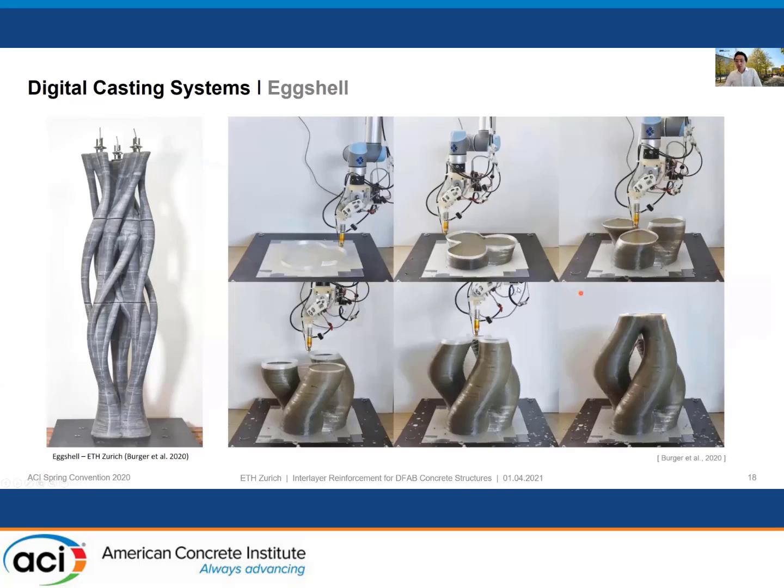On this slide, you see, I think, the Excel technology. Here, the minimum formwork is a 3D printed ultra-thin plastic formwork, which at the same time is filled. Then the formwork can be removed after casting, after the concrete has hardened, and can be recycled for printing a new formwork. Here is just a geometric exploration with a branch structure, where we can leave some openings in its elements to have post-tensioning cables.